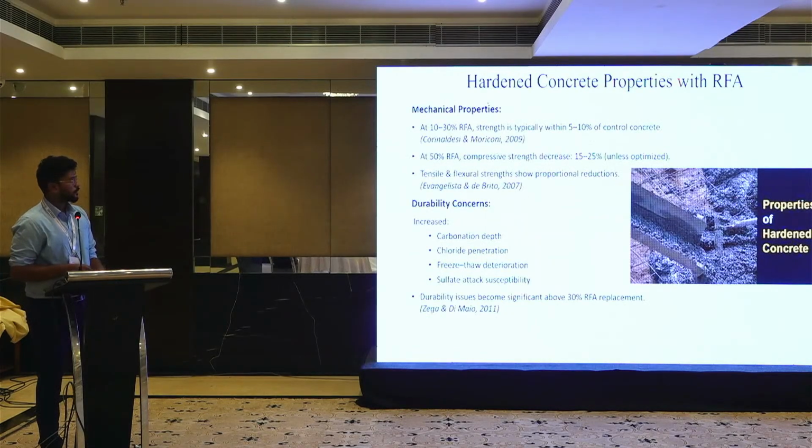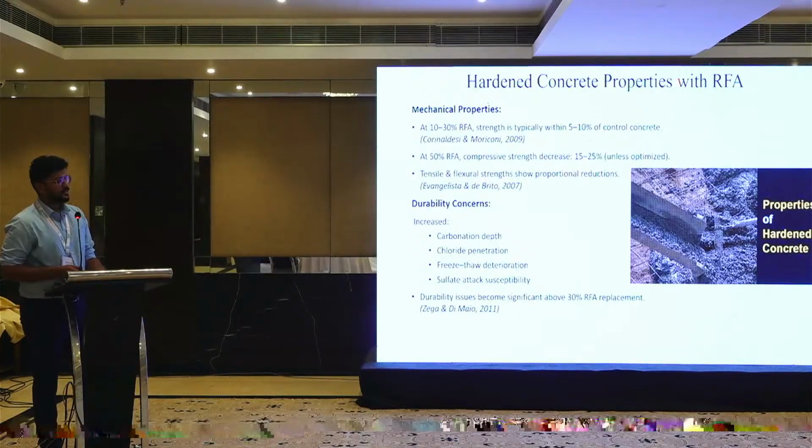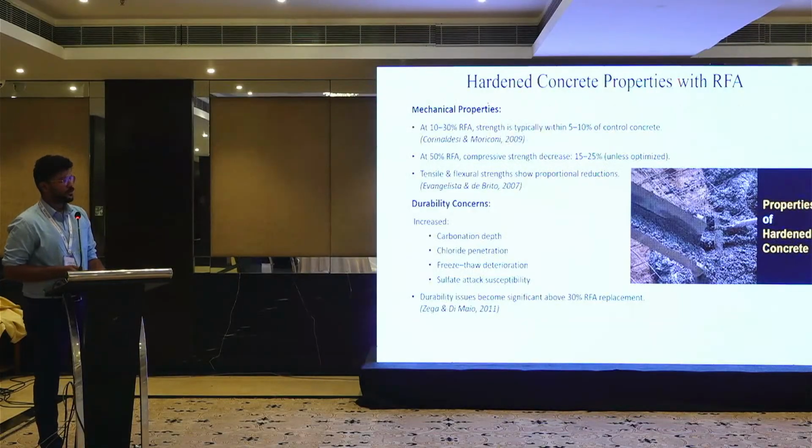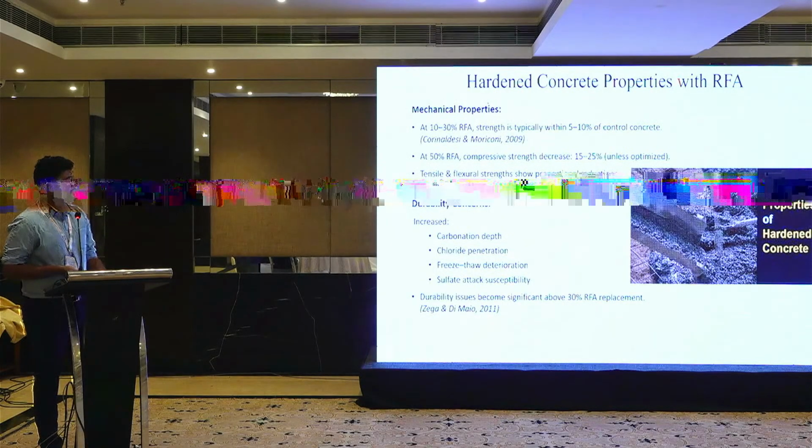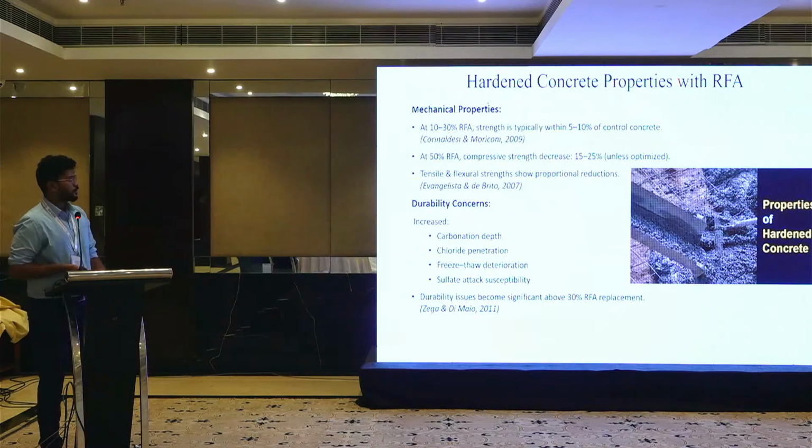Hardened concrete properties with RFA. At 20% RFA, strength typically varies by 5 to 10% from the control; at 50% it decreases by 25%. Tensile and flexural strength show reductions. Durability concerns include carbonation depth, chloride ingress, freeze-thaw deterioration, and sulfate attack.